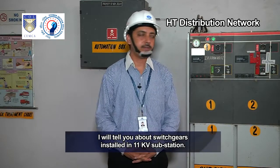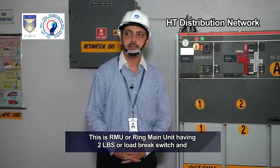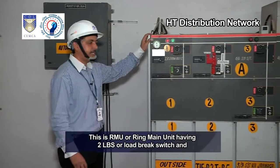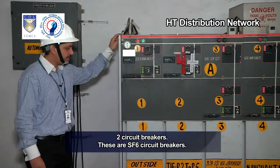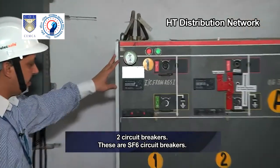Hello, I am Amrendra Kumar, Zonal Manager of Zone 571 of Tata Power. I will tell you about switchgears installed in 11 kV substation. This is RMU or ring main unit having 2 LBs or load break switches and 2 circuit breakers. These are SF6 circuit breakers.